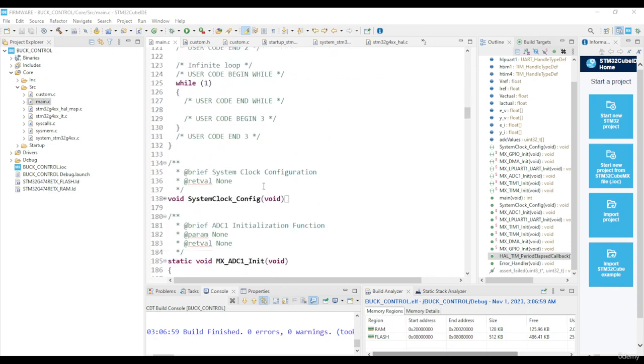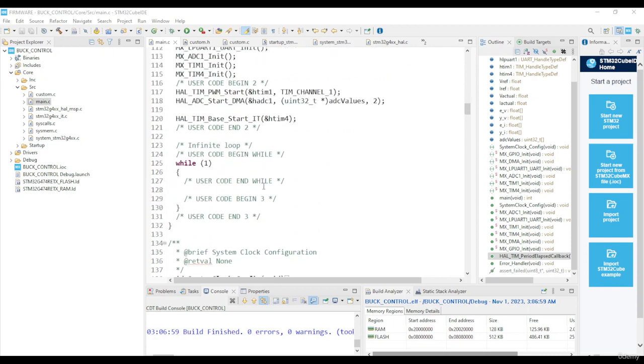And this really presents a lot of advantages for converters because you can essentially ensure that your converter is constantly operating in CCM, in continuous conduction mode. Additionally, you can actually save your MOSFETs. You can save your MOSFETs a lot of stress because inherently you are limiting the amount of current that goes through your inductor and by proxy your MOSFETs and your diodes as well. Essentially, the amount of current that goes through your converter.